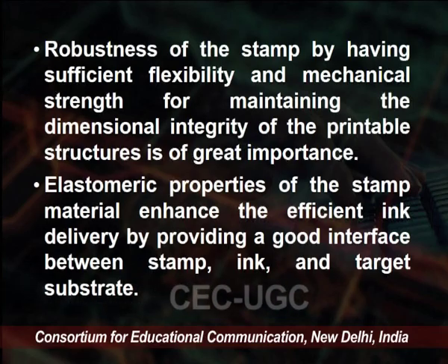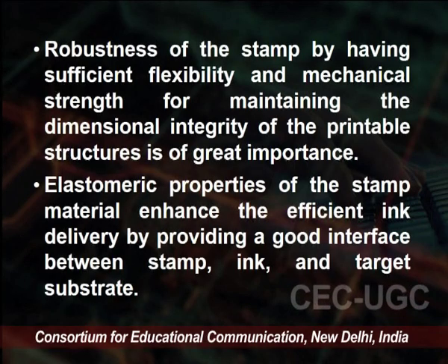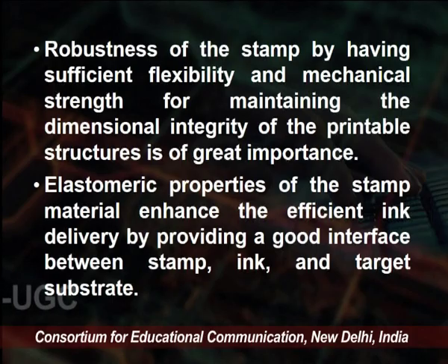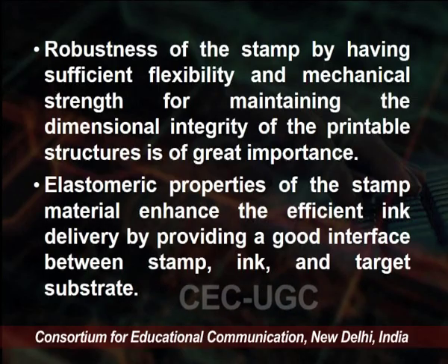Elastomeric properties of the stamp material enhance efficient ink delivery by providing a good interface between the stamp, ink and the target substrate. So the two important points are: first, it is flexible, and moreover it is efficient in providing the interface between the stamp, ink and the target substrate.